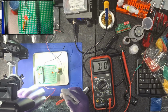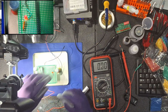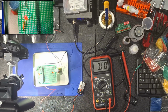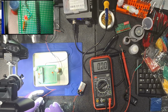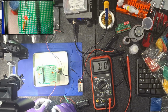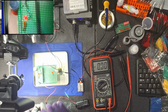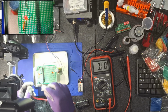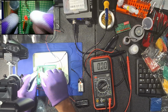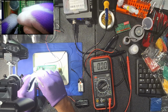Now I'm just going to connect the LED wires to the 9 volt battery. And just like that, the LED is fried. So the LED is totally burnt out now. If I try to connect the same 3 volt battery pack to the LED again, I should get nothing because this LED is dead. So we had 9 volts going to the LED that can only handle 2.2 volts, or well, it did handle 2.5, no more than 3. So it got 7 extra volts and burnt its core.